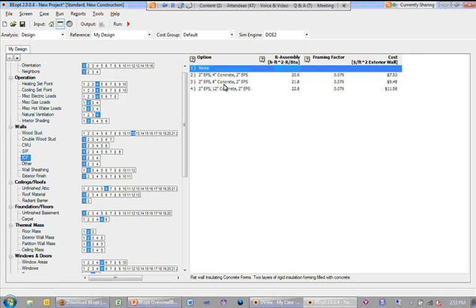The thermal lag of the concrete or the thermal mass in the ICF would not be expected to have much effect on energy, unless you're kind of swinging in and out of the deadband. In other words, if you're in a purely hot situation or purely cold situation, there's a lag in terms of the heat conduction through the wall, but it doesn't necessarily affect the energy.